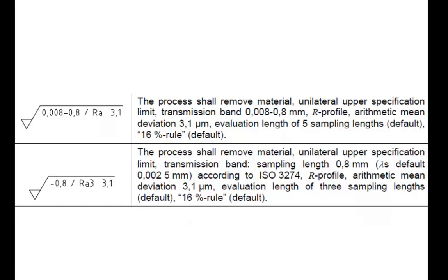During such a first measurement, if the measured value is below 70% of the roughness value shown for that surface on the technical drawing, then yes, only one measurement is enough to measure the roughness value.